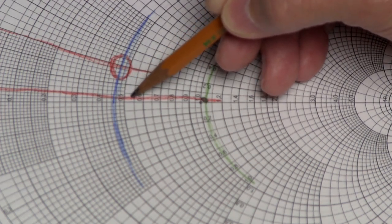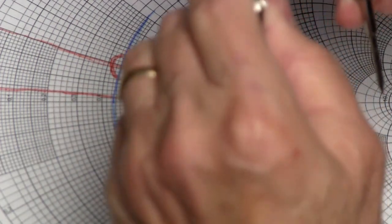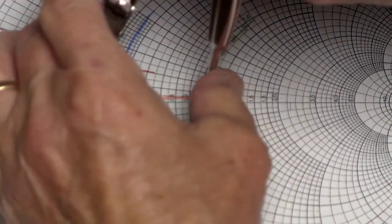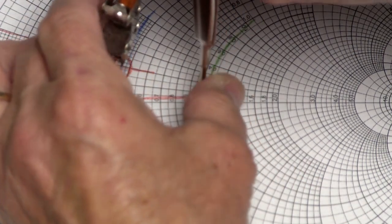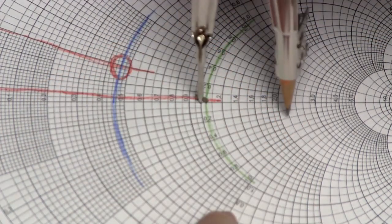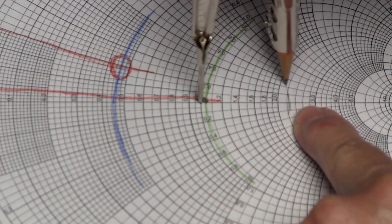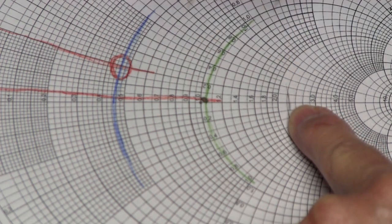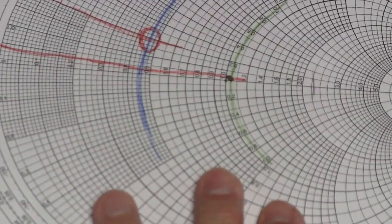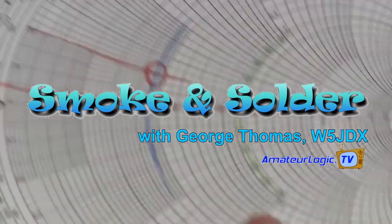Instead, I went below 0.5. How did I notice that I made a mistake several weeks ago? When I went to plot out the SWR curve, line my pencil up, when I went to make the circle, I noticed the SWR was a lot higher than it should have been. So there you go. Pay attention which direction the numbers on the chart go.